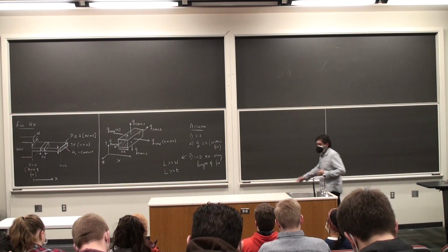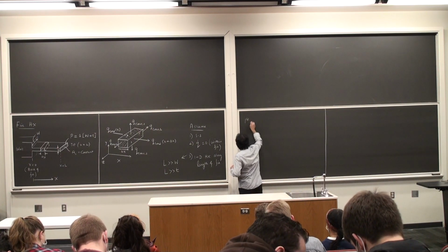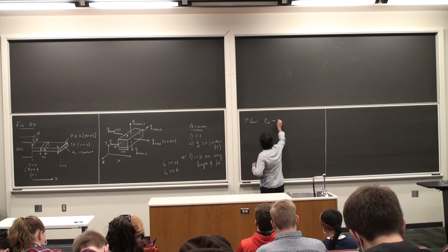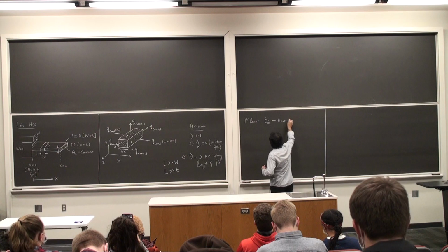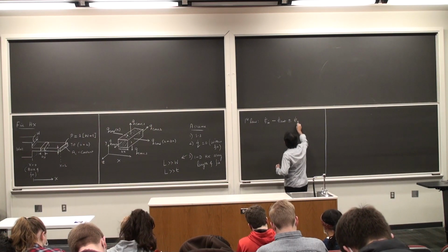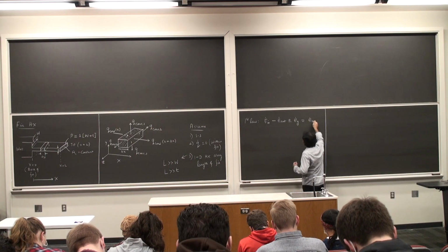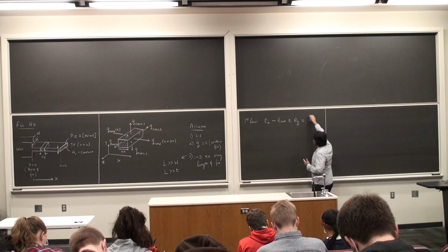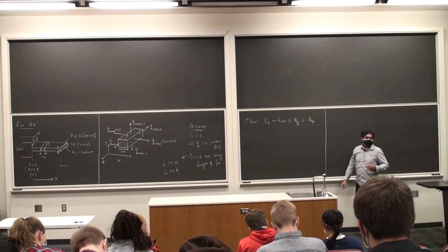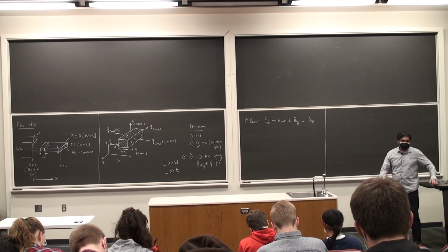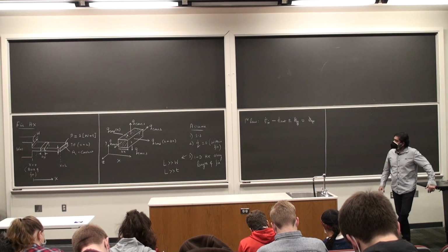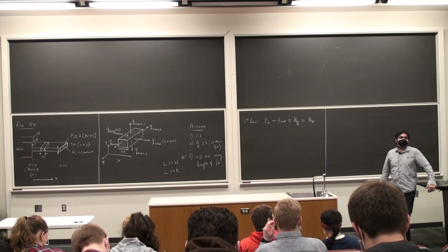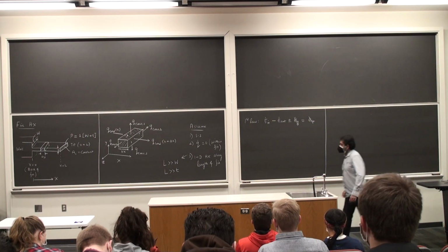Then we wrote down the first law. E dot in, E dot out, E dot generated, is E dot stored. There is no heat generation, there is no storage, because this is a time independent, steady state analysis. Question: we say 1D is along the length. Are we talking only about the conduction, not convection? Not convection. So conduction heat transfer.